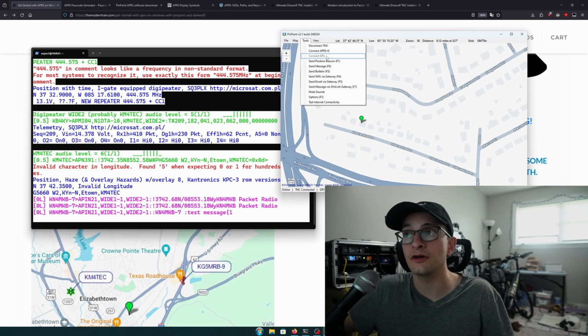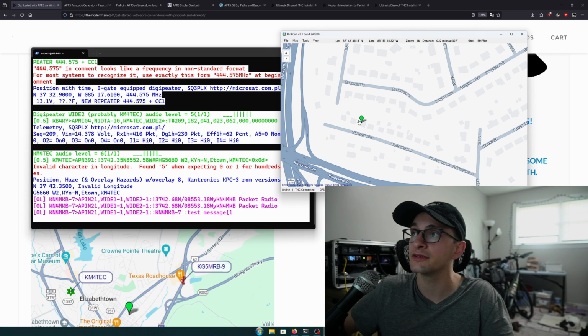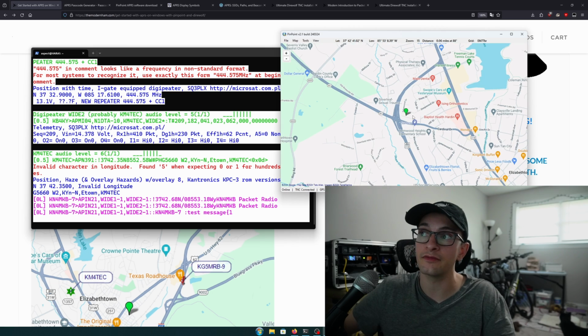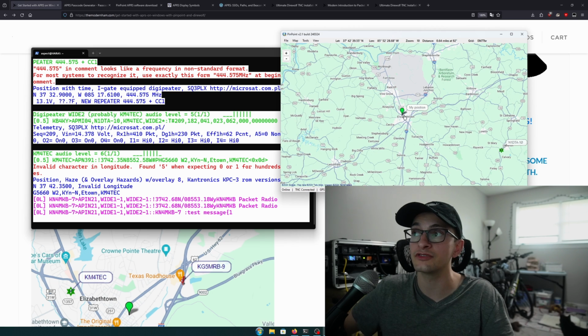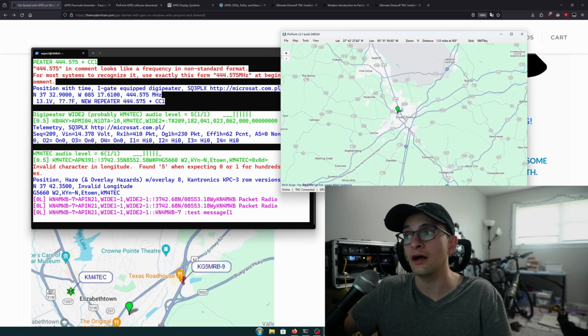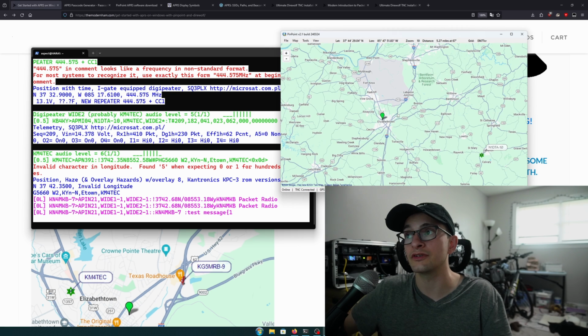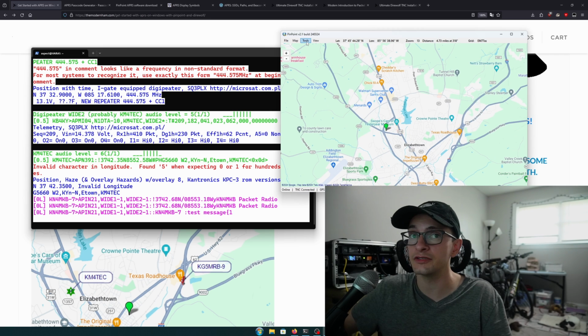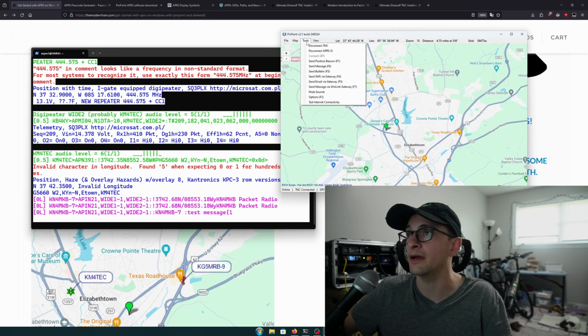You can also see this button here is Connect APRS IS. As long as you configured your passcode, you can hit Connect APRS IS. And now, whatever you hear is getting forwarded to the information system. So you're serving as an IGate for your local area, which is nice if they don't have one. But you may also start seeing information from the information system come back to you to populate on your map from the internet.